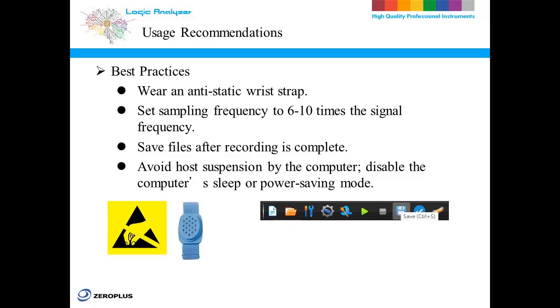After recording, always save your files. It's not just about keeping the analysis results, you'll also have them handy for double-checking or comparing later on. And one last key tip, make sure the computer doesn't interrupt the instrument by going into sleep or power-saving mode. I'd suggest turning off your computer's sleep function altogether. It keeps everything stable, especially during those long recording sessions.